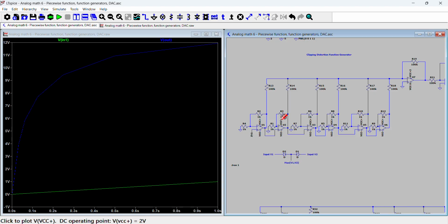However, what happens if the voltage starts getting a little bit too big? The voltages at the ends of these amplifiers, because they're fed in from the previous stage, will be multiplied by all of the previous stages, and it becomes so high that the later stages can no longer amplify, so it ends up clipping the voltage off. And so instead of outputting the previous stage multiplied by 2, this stage will output VCC, which is a constant voltage.